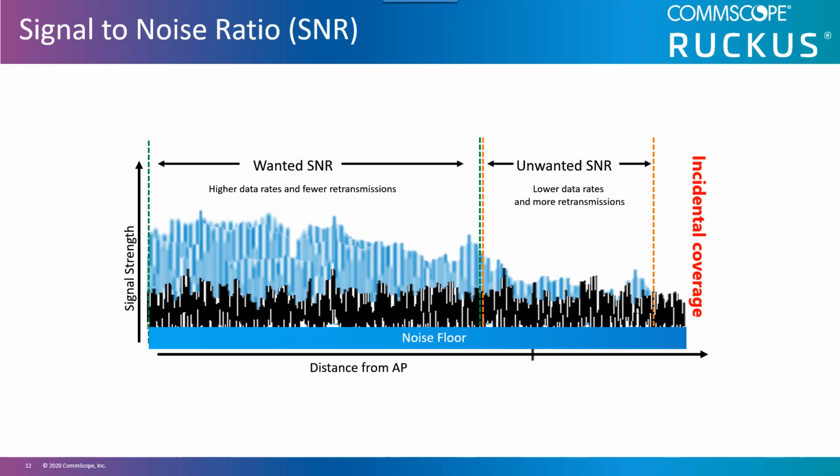A signal-to-noise ratio, or SNR, is defined as the difference between the noise floor and the signal in dB. This diagram shows the signal strength over distance as a curve that has the best signal strength closer to the transmitter. The diagram also shows noise within the space. The noise tends to be the garbled background RF noise or signals that come from everything around the receiver, including such things as the sun and stars, to man-made interfering devices such as Bluetooth headsets or remote controls.